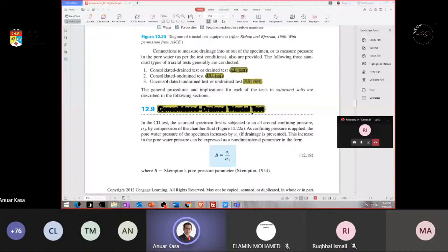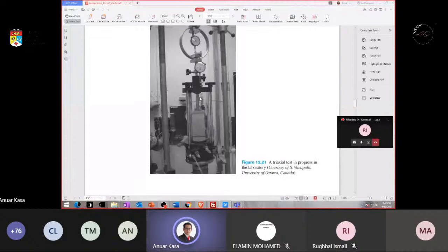So it takes time. And this is the triaxial unit. This is a sample. This is a container, and here the load cell, or the ring here, will be pushed. Pressure is applied to the ring, so the ring bends a little bit, which gives the value recorded here. So we know the normal or axial stress.